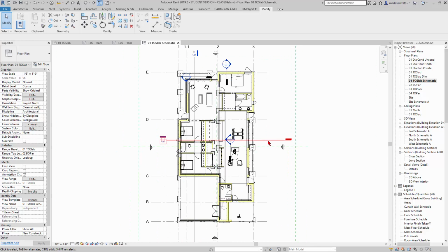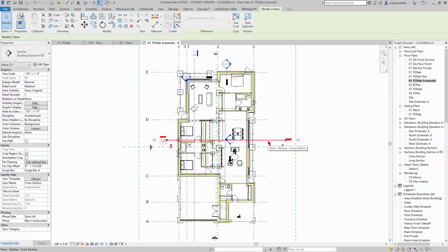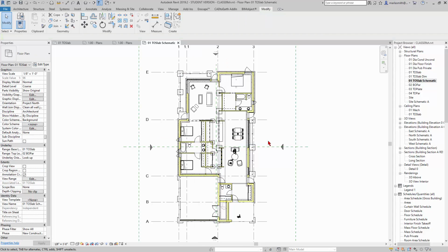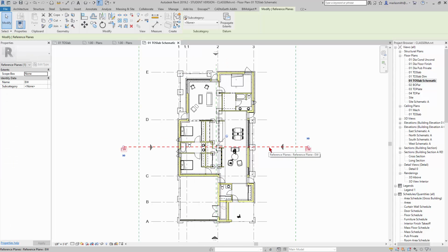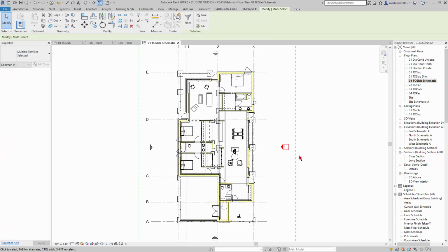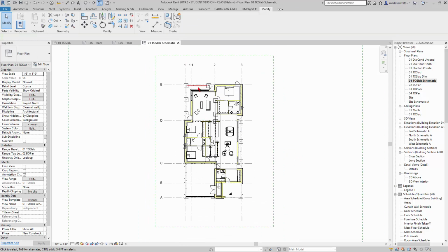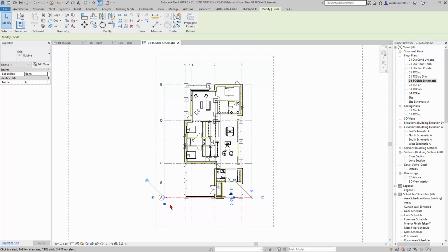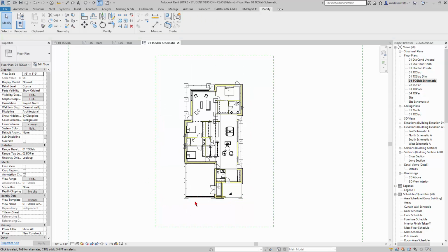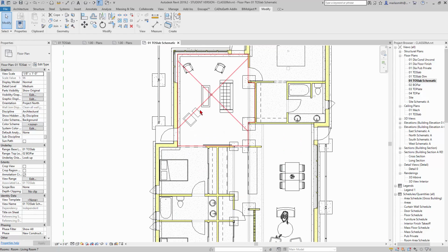First thing I'm going to do is just select the sections and VH, so hide that category, just VHing things that I don't want in here, right? The rest of this looks okay. I'm going to come down, maybe I don't want these guys in here either, the grids, all of that. I'm going to come down and maybe change the detail level to medium, so I've got a little bit more definition in what I'm looking at.